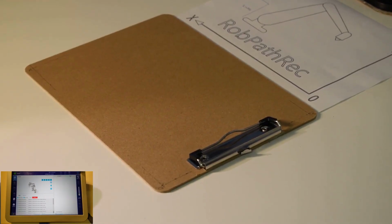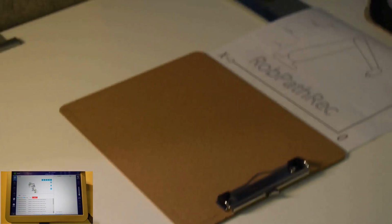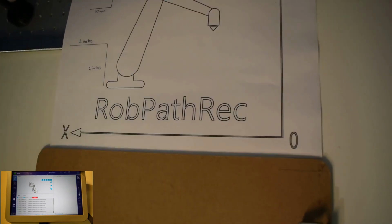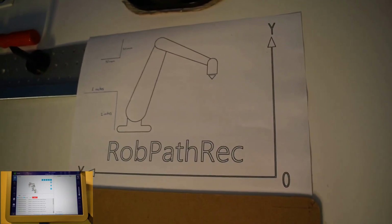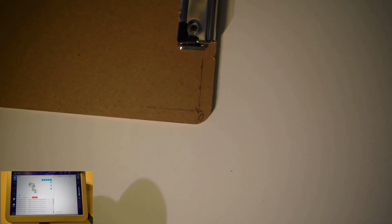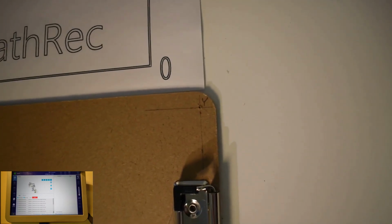Okay, as next, we have to define a user frame. The user frame is the working area where we will use further on. I will show you with this example that we are using a similar coordinate system like this origin X and Y, which I have it on this clipboard. This is the origin. There is my X and there is my Y point.